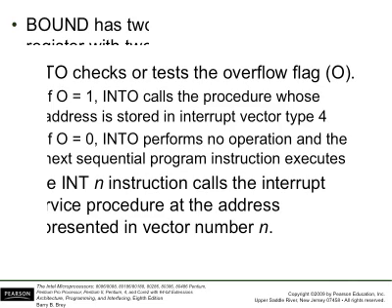With this instruction, the processor will go to whatever address is stored in the interrupt vector table at index 21, or in this case n. It'll use that as the new address and go to the special program to complete the software request.